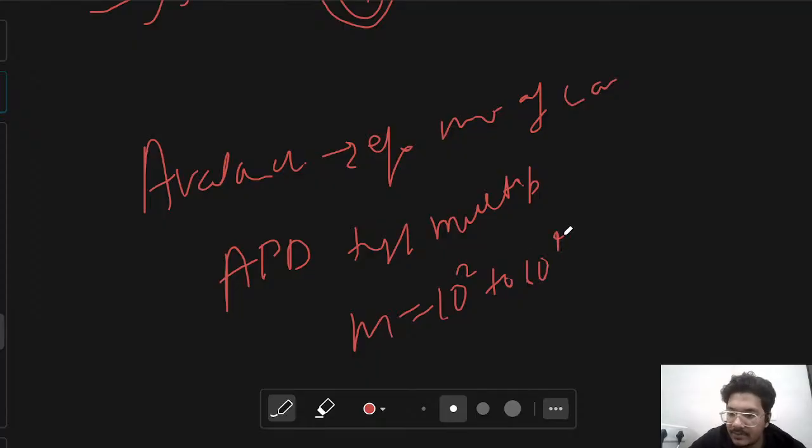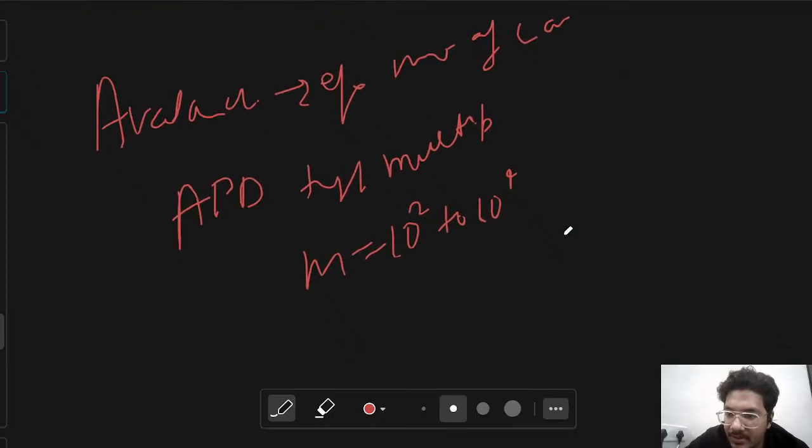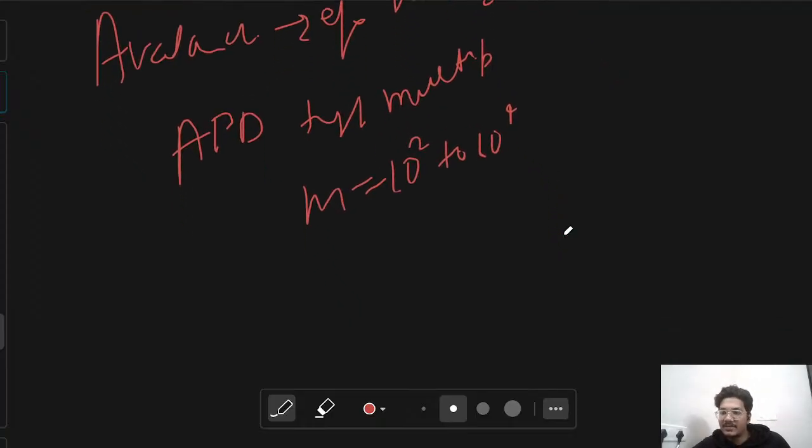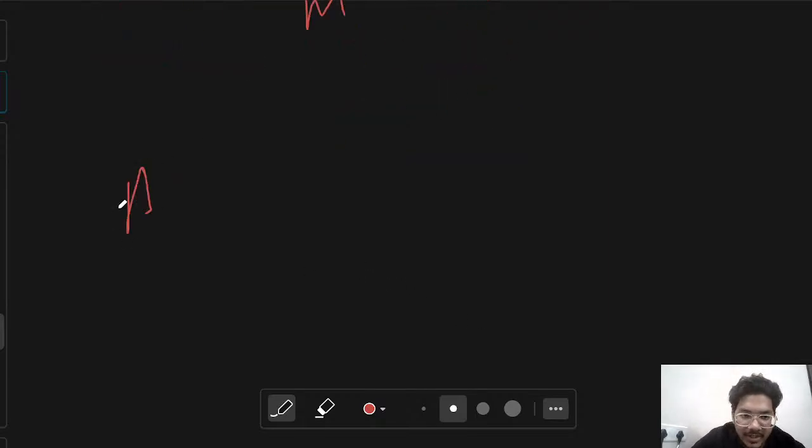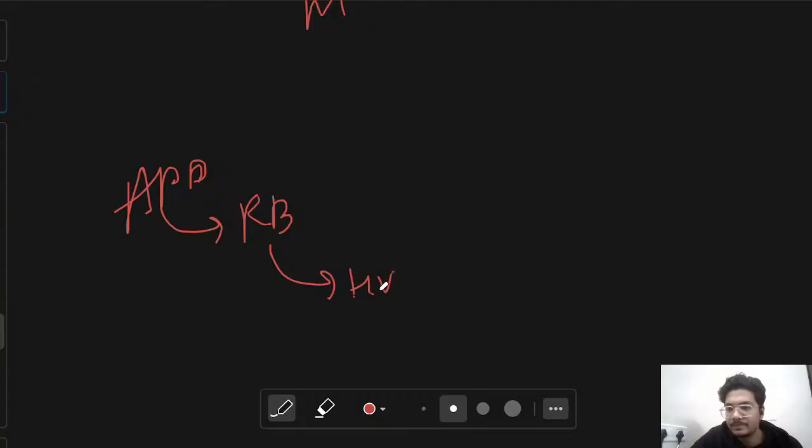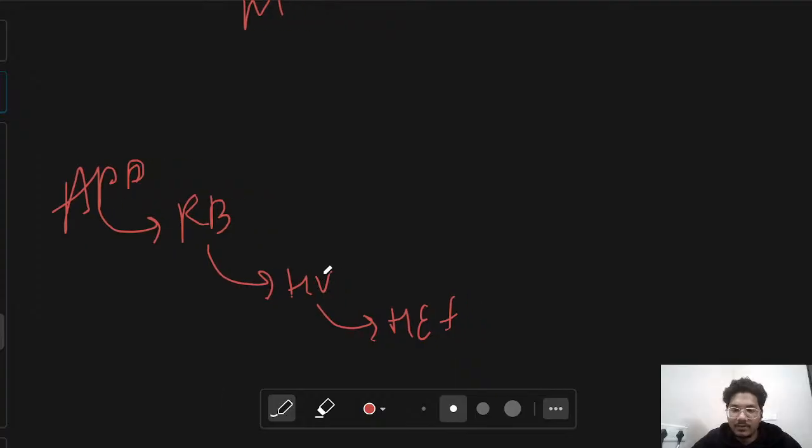Now the reverse bias requirement. The avalanche photodiode must be reverse biased at high voltage to create a high electric field. Typically the biasing voltage is approximately 50 to 400 volts. And the newer APDs operate at 15 to 25 volts.